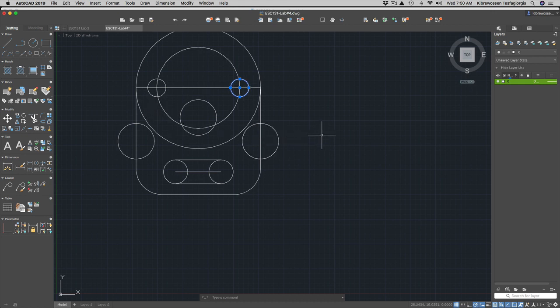Then I'll use the rotate command, specify the base point. The base point is this. Then I need to specify an angle, which is 30 degrees. Okay, then I'm going to do the same thing with the other object. Select object, this guy, base point, this, then my rotation angle is probably -30. Okay, why negative? Because it's in the clockwise direction.